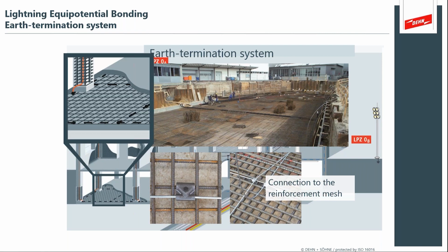And if you have something like this pillar that is casually bonded together, if there's lightning currents flowing through that rebar, it will arc and spark within the buried concrete, which will spall the concrete and cause failure over time.